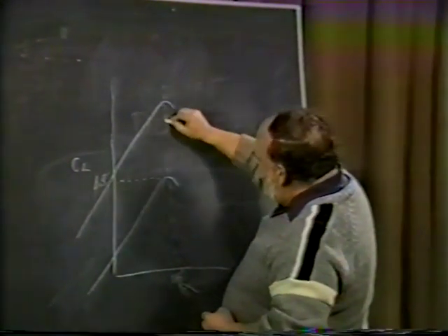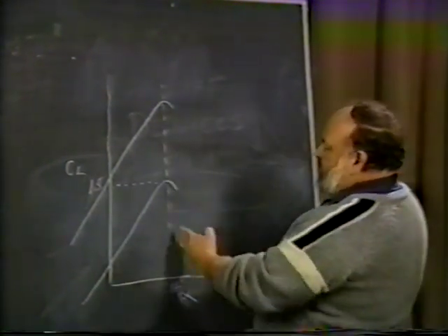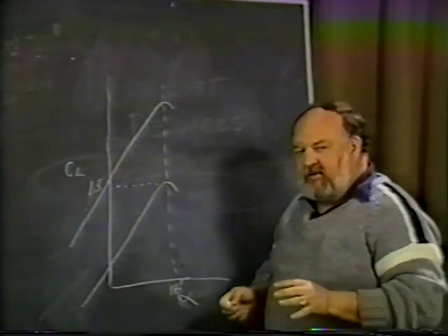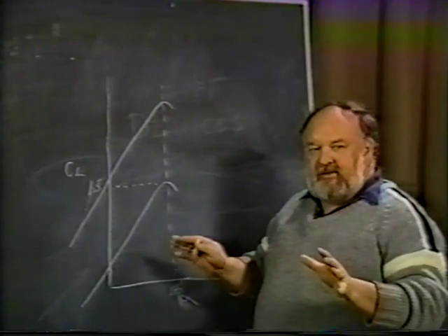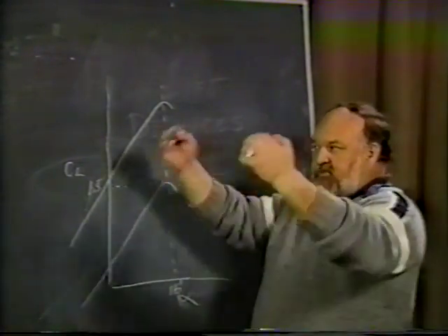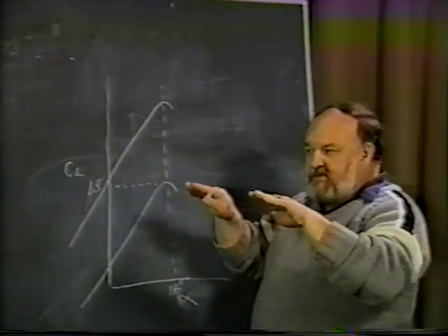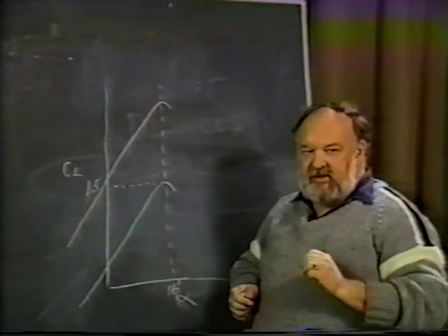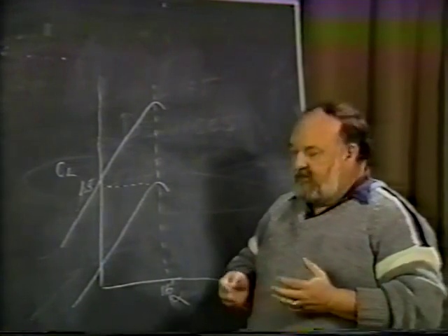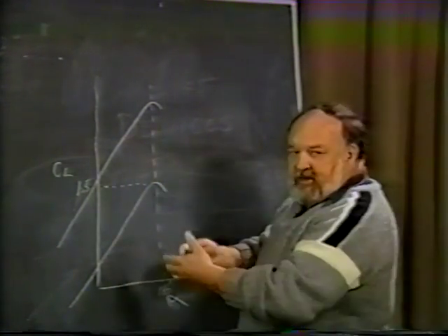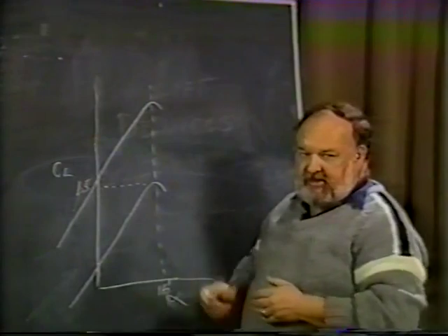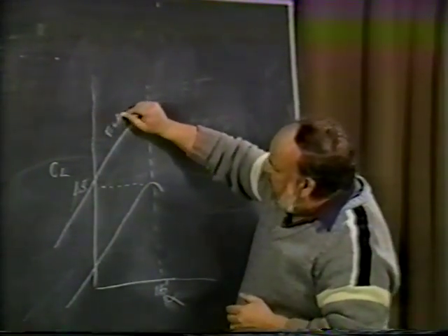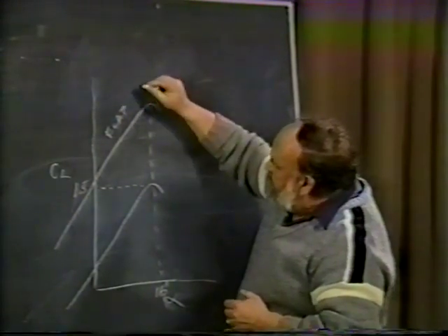But in most cases, the angle of attack that the wing will stall at will be pretty much the same. This is somewhat understood in the fact that here you are with the trailing edge of the wing, you put these devices to induce more air to come over it, but the wing itself can only go to so much of an angle before the flow over the leading edge causes separation. So the flaps produce a lot more camber, a lot more lift, but not changing the angle of attack itself. So this is because of the flap at the trailing edge.